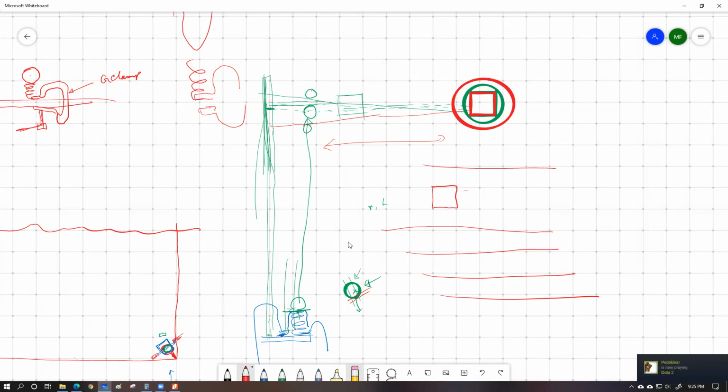So in that case there is no reduction of potential energy because of getting closer. There is an increase of potential energy because of the increase in intermolecular distance, and there is also an increase of potential energy because of the weakening of the intermolecular force. So both of these factors, for a solid metal into liquid metal, contribute towards a positive increase of potential energy.